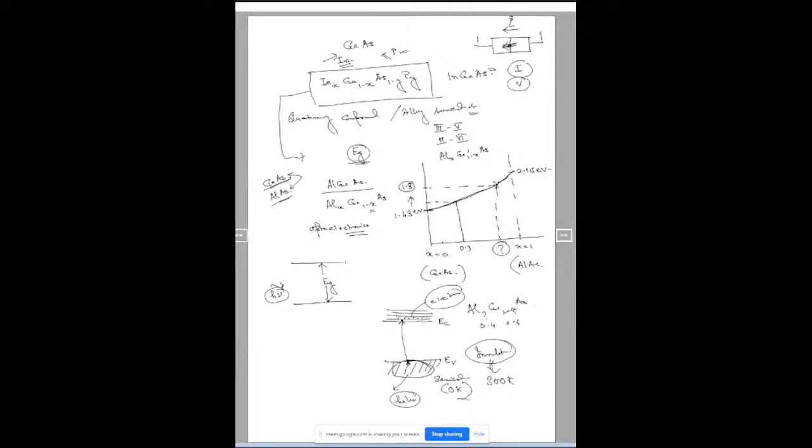But back at the band structure level, you'll find that something different is happening: how these electrons are moving through different quantum states available to them, and how the holes are moving. Basically, electrons are occupying those positions, and that's how conduction is taking place in the valence band. But in a macroscopic description, we simply treat the electron as negative charge, minus Q, and holes as carrying positive charge, moving in the opposite direction.